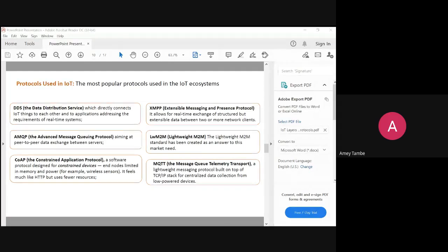So what will be the ideal situation? If you don't bother about the recipient, or if you don't bother about the feedback, so it is just a broadcast session. Like in our case, if we wanted to take out the temperature and display it on our remote side, then we don't require a feedback mechanism for whether that temperature is displayed or not. So that time we can use the least reliable mode, and we can achieve greater flexibility with less consumption of power.